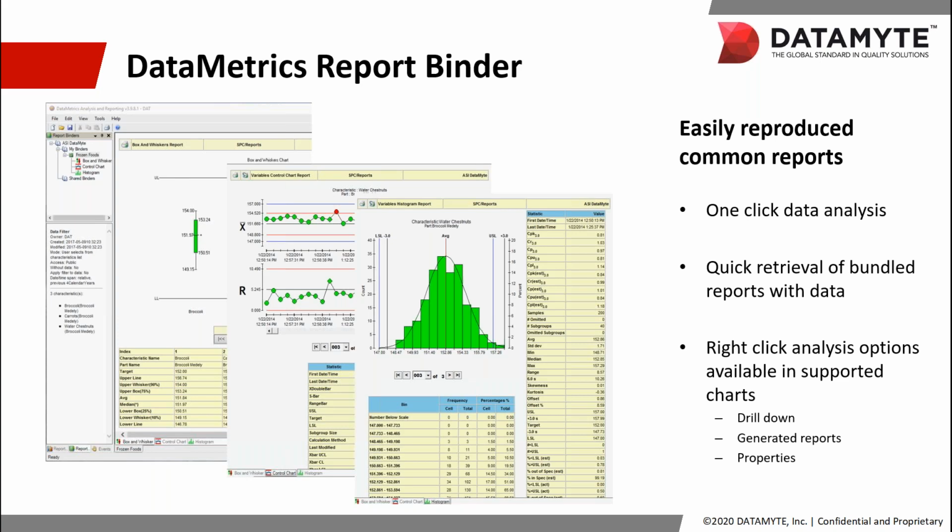I used this to help a customer generate a monthly report recently. They needed only the characteristics labeled average, but there were thousands of characteristics to sort through, and to select only those with that name was onerous, especially since some of them were abbreviated to AVG. So instead of doing that, we created a user-defined report with the required capability statistics and bundled it with a data filter pulling all data from the previous month. Once the report populated, we filtered the characteristics for those containing capital A, lowercase v, g. This gave exactly the desired information, capturing both average and AVG data.